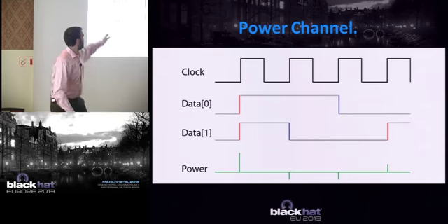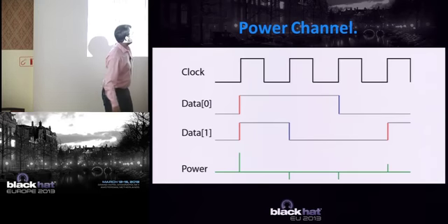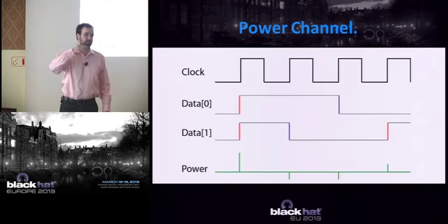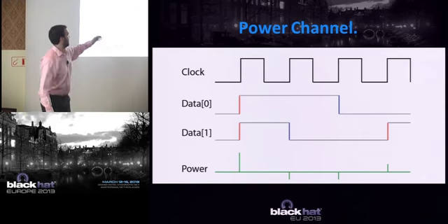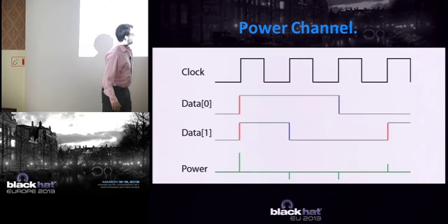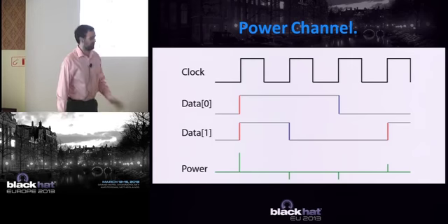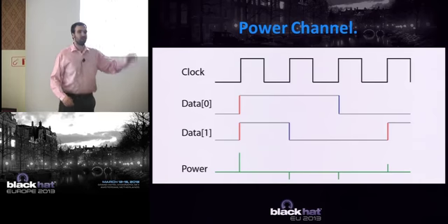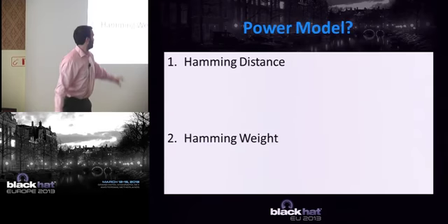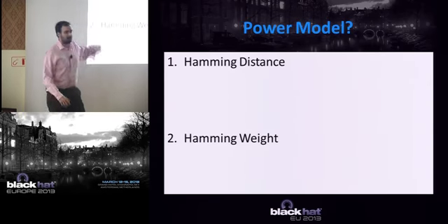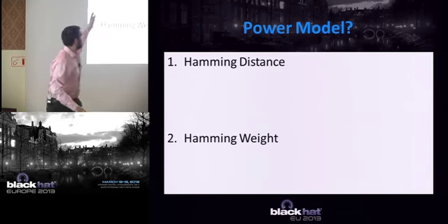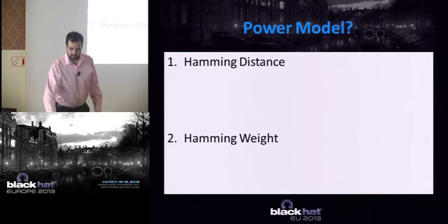So what they do is in between these two states, it's pre-charging it to halfway. So it's always putting it to this half state. To go from this half state to either positive or negative is going to take half the energy. So now when we go from all ones to all zeros, it's actually going to this half state in between and then goes to all zeros. An artifact is this, that every clock cycle, we can learn about the number of ones that is on the data bus, which is what we call the Hamming weight model. So the Hamming weight model is just saying that we always know the number of ones on the data bus. The Hamming distance is saying we know how many lines are changing on every clock cycle.